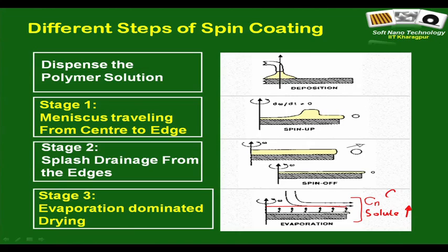And now it is very important to understand that you have actually taken a solvent which dissolves the solute. So, why should the solute deposit on the substrate? Well, the solute will start to deposit on the substrate only when the intrinsic concentration of the solute matches the saturation concentration. So, due to gradual evaporation of the solvent,